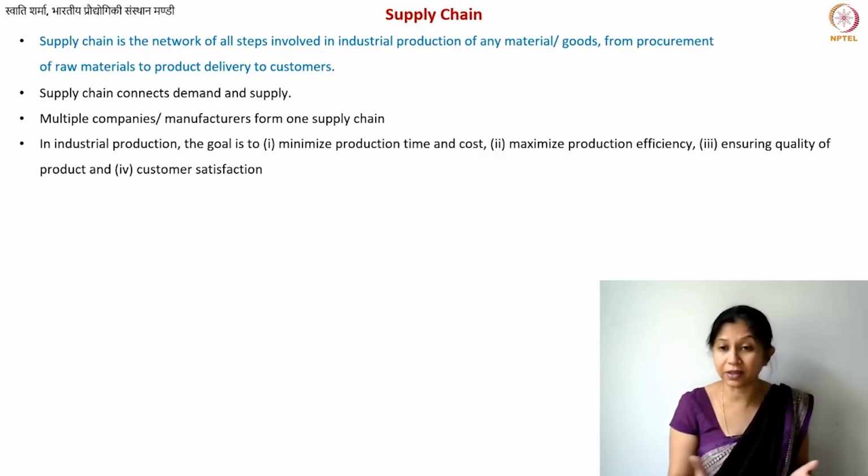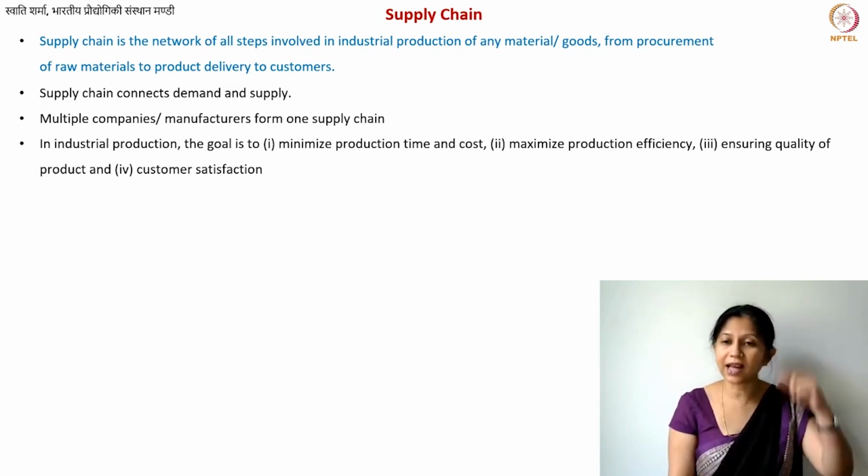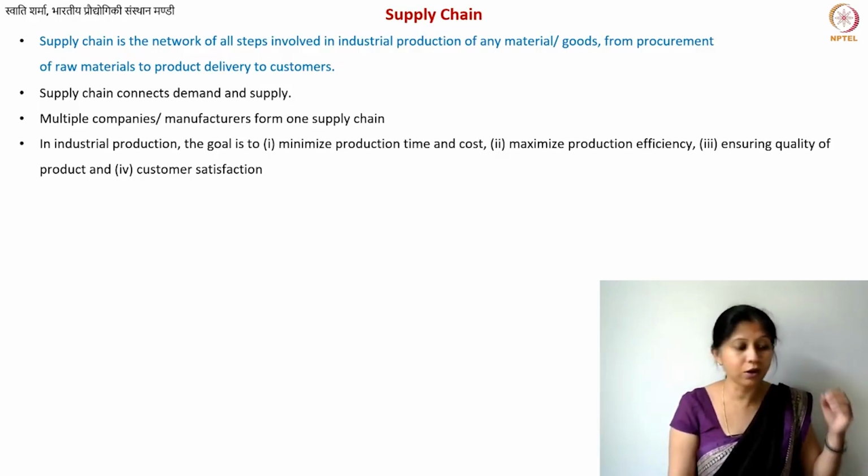This often happens in the case of carbons, because when you're making carbon fibers, or anything that is graphitic, the last steps of graphitization are the most expensive, most energy consuming steps, because you need to go to temperatures as high as 3000 degrees. And these processes are also relatively very, very slow. It may take several days to convert a certain set of carbon fibers into graphitic carbon fibers.